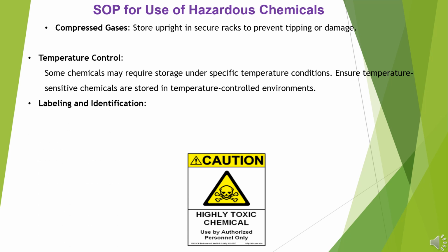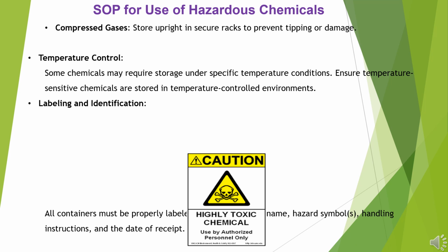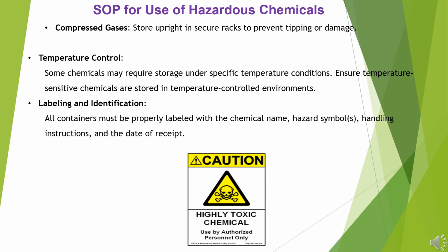Labeling and identification. All containers must be properly labeled with the chemical name, hazard symbols, handling instructions, and the date of receipt.